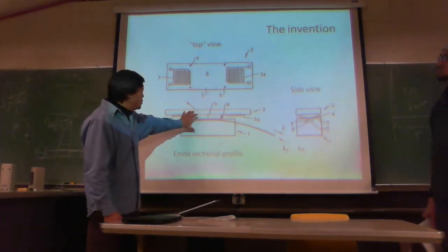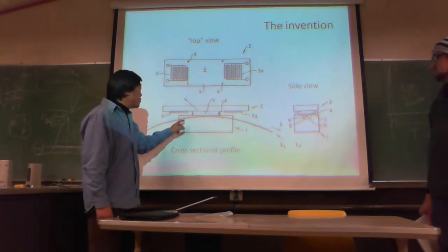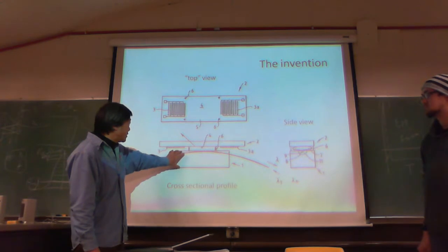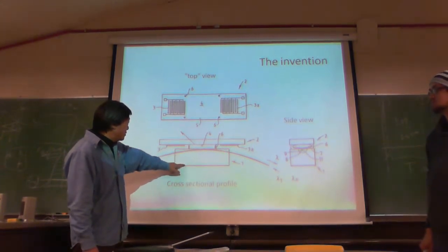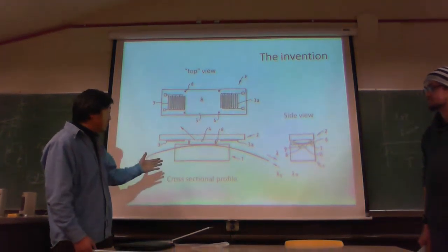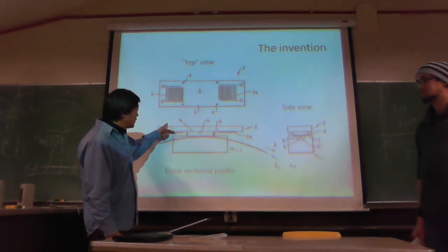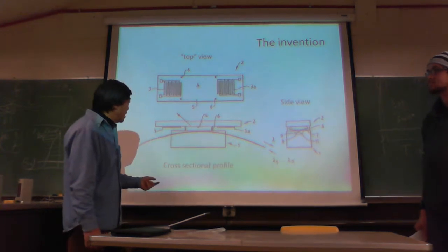So this one unit, the side view looks like this. They call this the transmission substrate. The entire thing is made of the crystal, like I said. They call this transmission material, the medium. And in general, the surface acoustic wave is created on this side, on the surface of this medium.